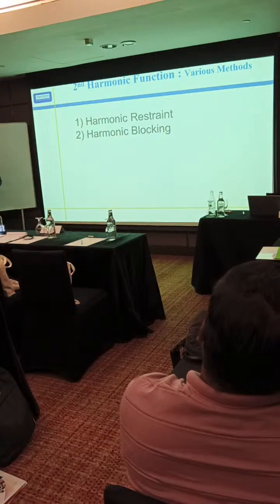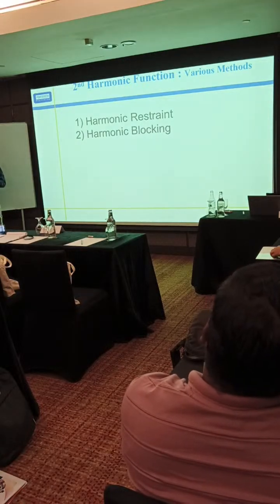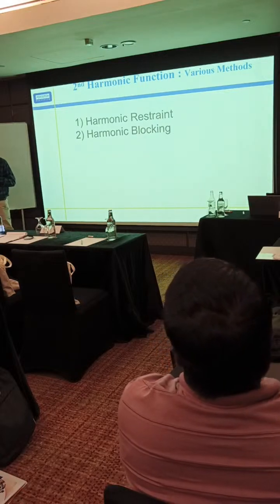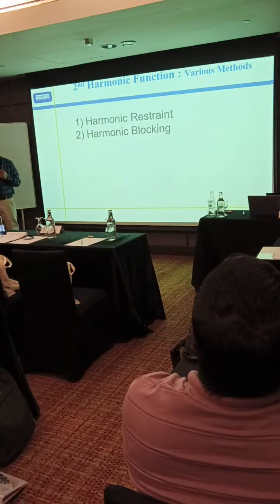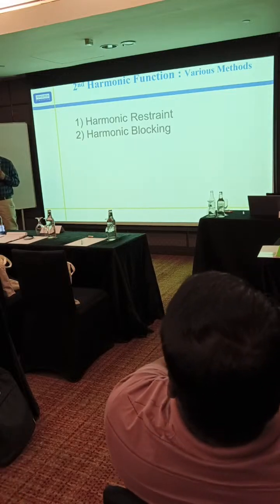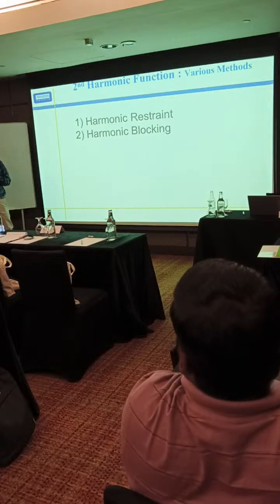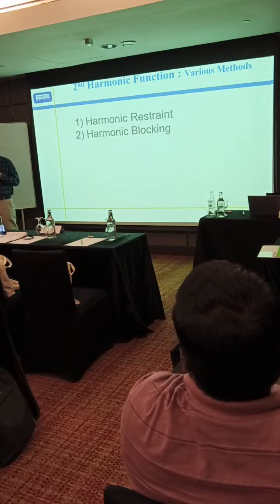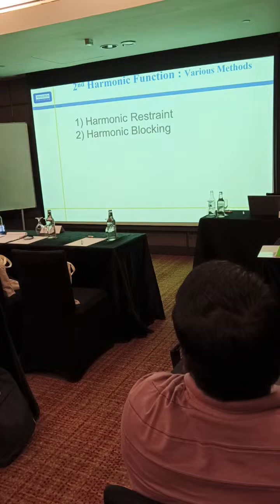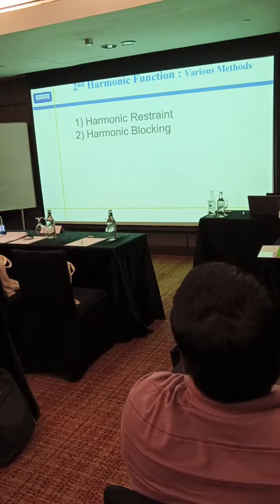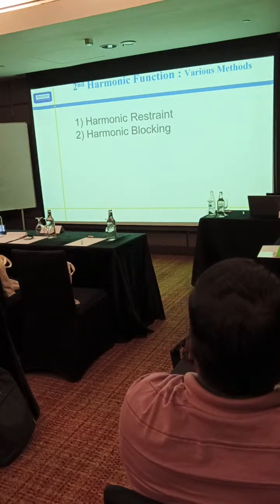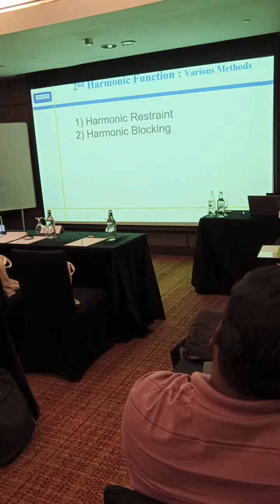If you are in the power sector and frequently charging transformers, then most probably you have faced this problem. Even though sometimes everything is okay, in that condition also sometimes other protection that does not have the harmonic blocking then trips. How this harmonic component affects our testing and our transformer charging condition, we can understand in this case.